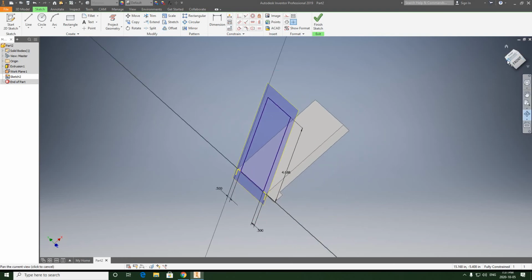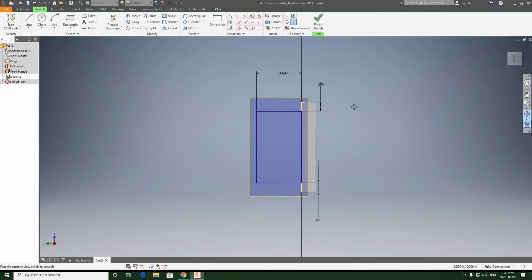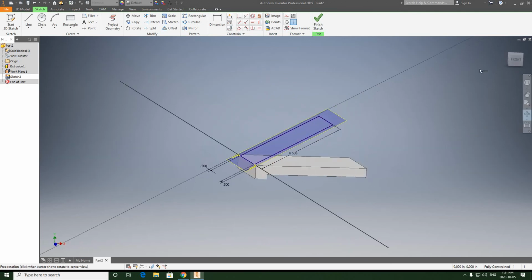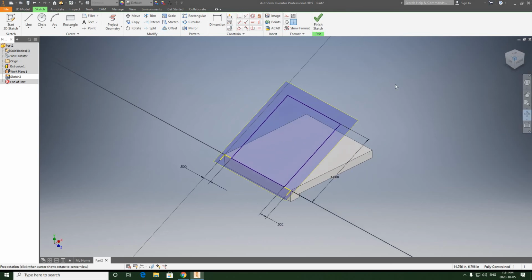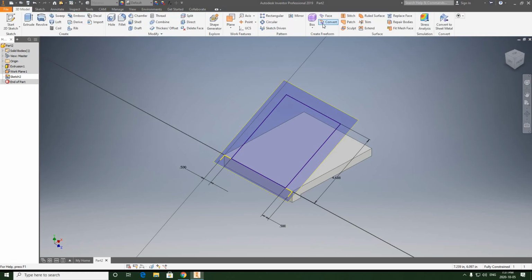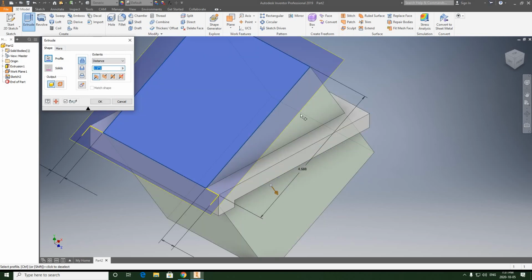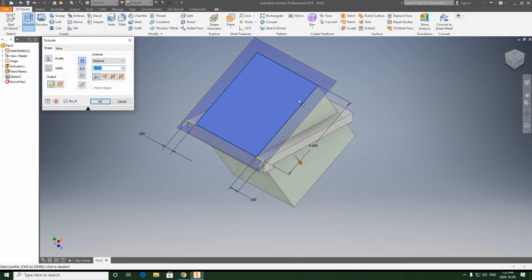Now this is going to be a new way to extrude. So what we can do, let's go into an ISO view between left and front like this. We're going to hit finish sketch, and we're going to hit extrude. We're going to select. Now see what it wants to do? It wants to force this extrusion through the base, which is unacceptable.